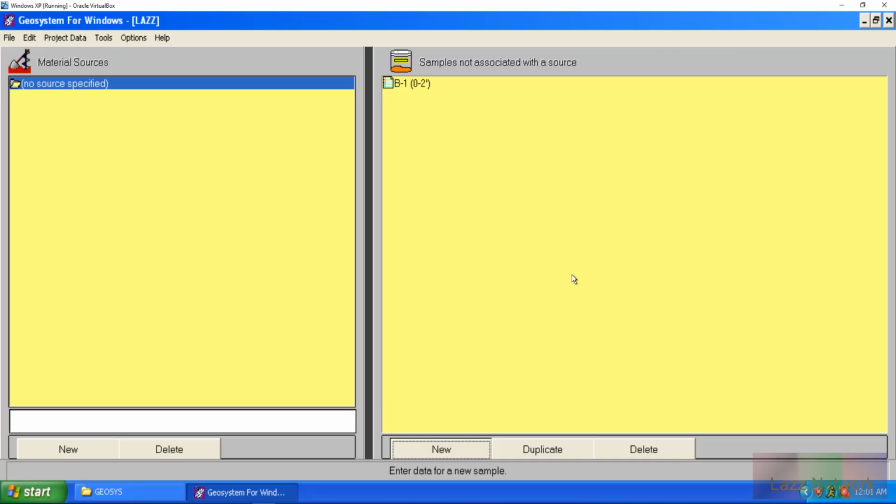Usually people call it particle size distribution if it's a hydrometer and whatnot, but especially when you do a hydrometer test, you account for every particle that is in that sample, big or small or non-existent. Everything in that sample needs to be accounted for in the report, so the engineer or the contractor or whatever the intended use is knows, because if they're asking for a hydrometer, it's extremely important because they need to know all that data, especially the clays and silts.